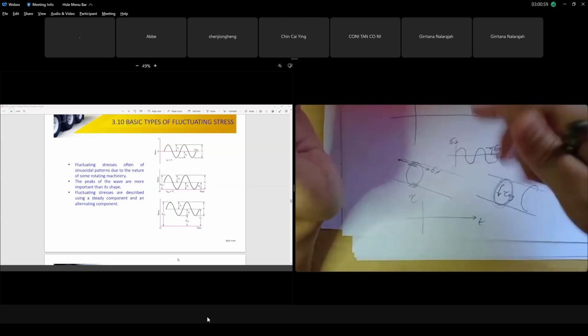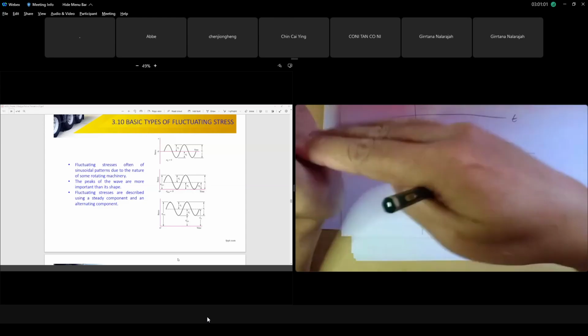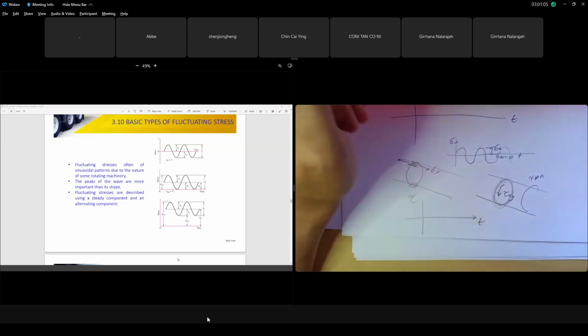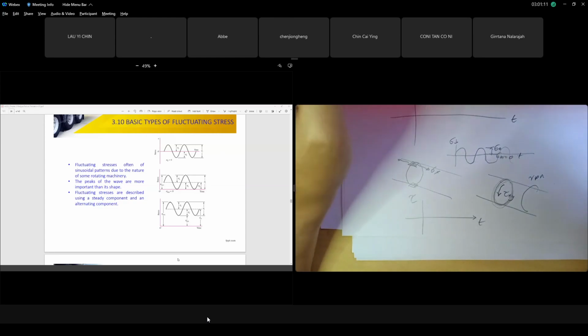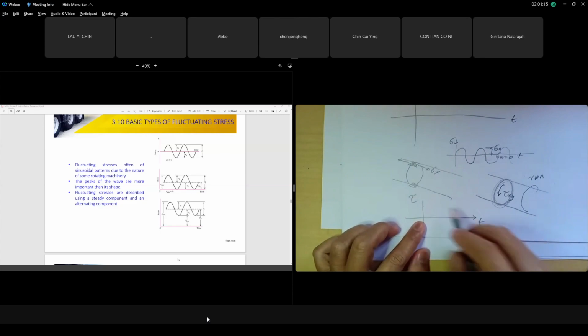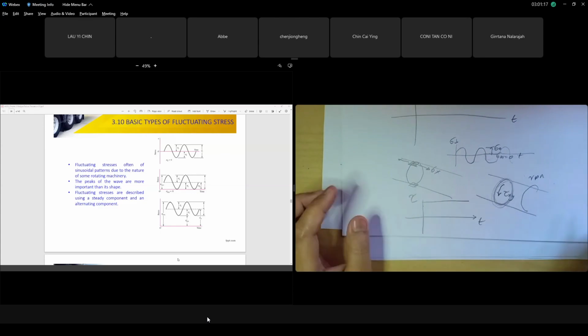And the shaft is rotating. Through time, the shaft rotates. Through time, does the torsional stress change magnitude or remain the same? It remains the same, right, class? Understand? It's constant. I mean, the torsional stress through time is a straight line. Clear?